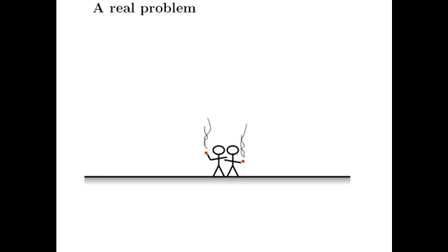So the problem's very simple. It's this smoker's problem. Okay? We've got these 2 people who are having a cigarette. So they're creating a contamination. And the question is very simple. It's a problem, I guess, that many airports deal with. I'm going to add an extraction fan. Okay, so I'm going to remove mass flow from some point in space, and I want to work out where's the safe limit for somebody else to stand and not be contaminated by that cigarette smoke.